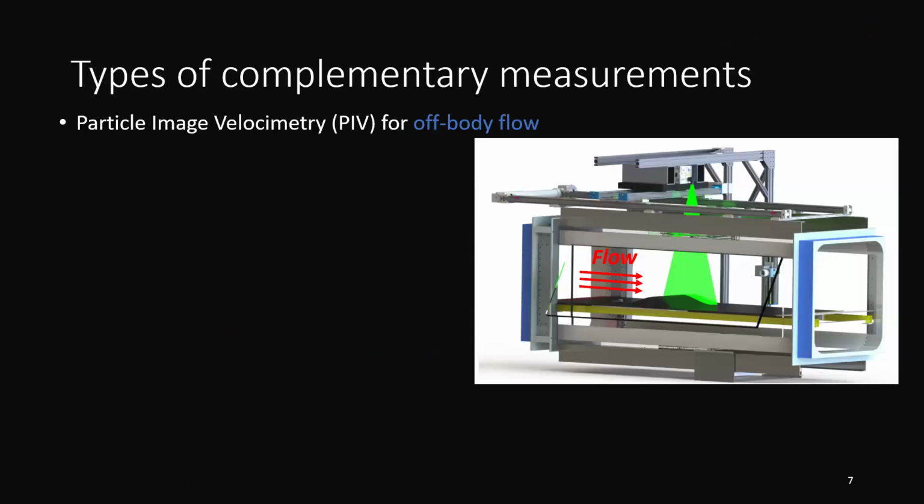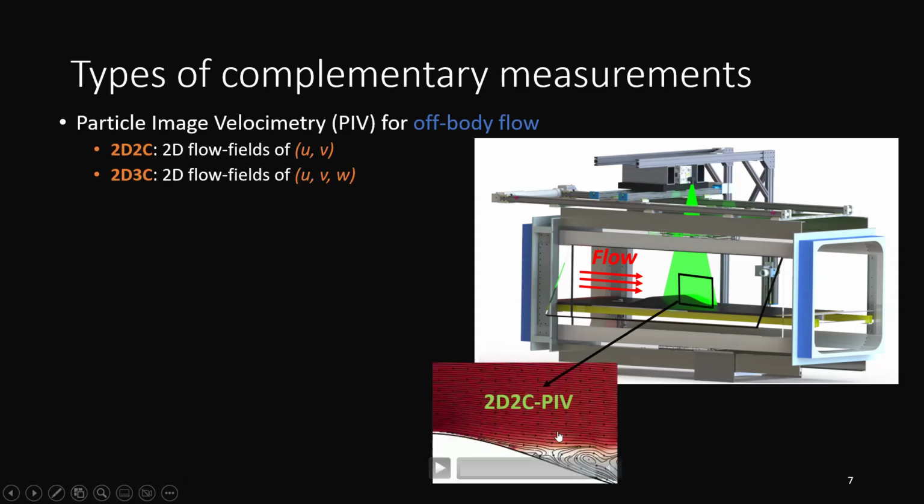All right, so what are the types of measurements? The first one I showed you was fluid imaging. This is particle image velocimetry. We're trying to extract velocity fields of a fluid flow. So this is a model inside the test section of a wind tunnel, and you have flow moving from left to right, let's say. You have a laser system on top, and you have a synchronized high-speed camera. Effectively, it produces a movie. Well, this is post-processed, of course, but you have snapshots of a two-dimensional, two-component velocity flow field, called 2D-2C, of the PIV flow field.